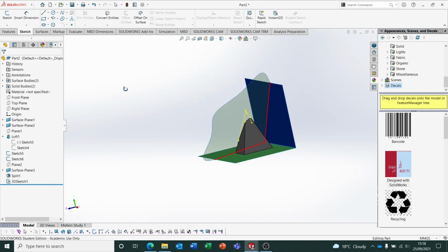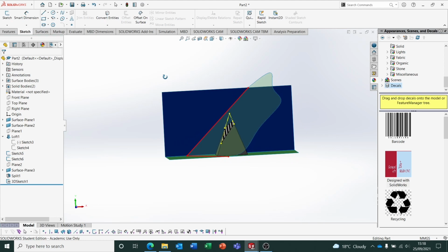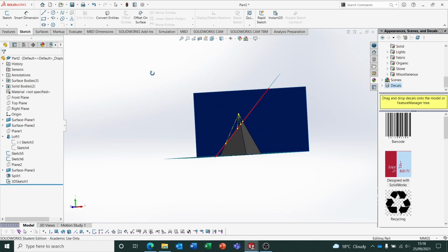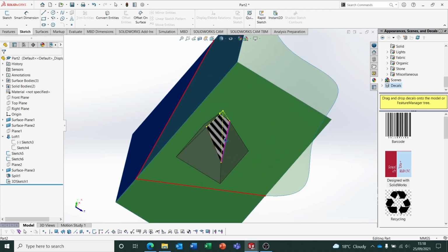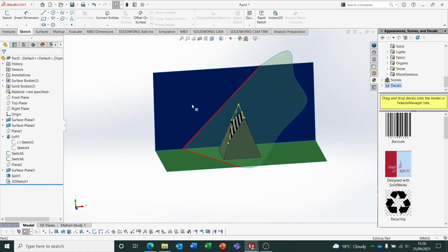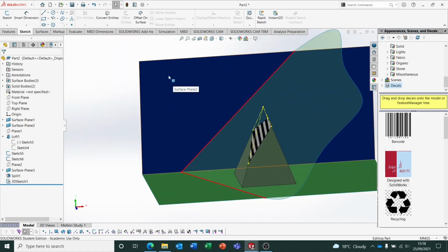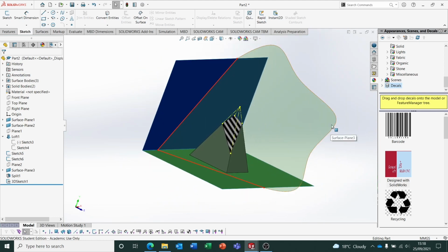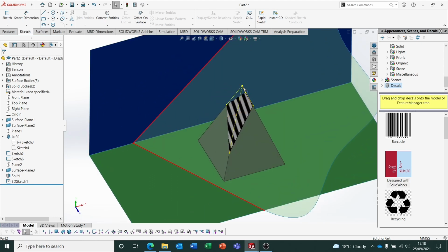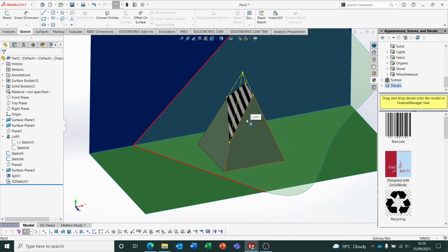So now, as you can see, it's a lot easier to see what our shape was like starting in plan and elevation. What we can see when we look along that oblique plane, how we can get that cut, and then what we see when we look normal to the cut surface. And we can see that cut surface very easily with the diagonal lines. Now, what I want you to do is make sure to label your vertical plane, your horizontal plane, label the traces, horizontal trace and vertical trace, label the oblique plane, and you can label some of the points there if you want as well. That's not crucial, but label that apex anyway. And you could also label the cut surface.